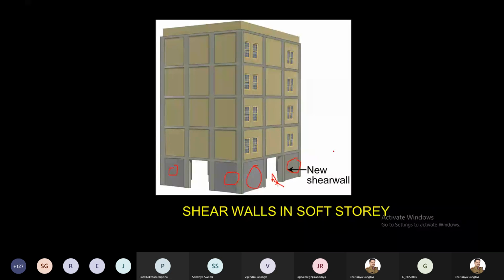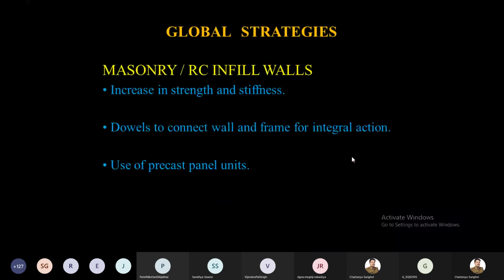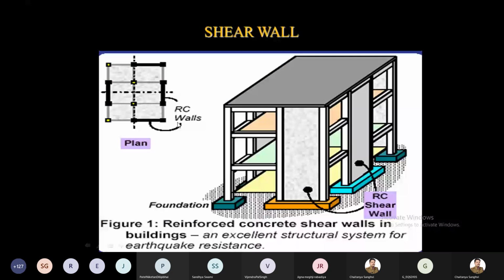So you have to design the shear wall in such a way that you have enough opening, and generally 20%, 30% shear wall will work, and the rest you have to plan in such a way that parking is possible. This shear wall, we said, should be placed symmetrically, right? This is the most important aspect. If you place the shear wall on this side, the shear wall should be placed on the other side also. It must be symmetrical in plan. It's required.